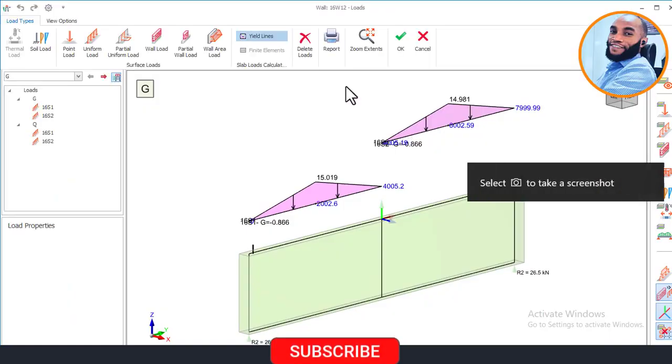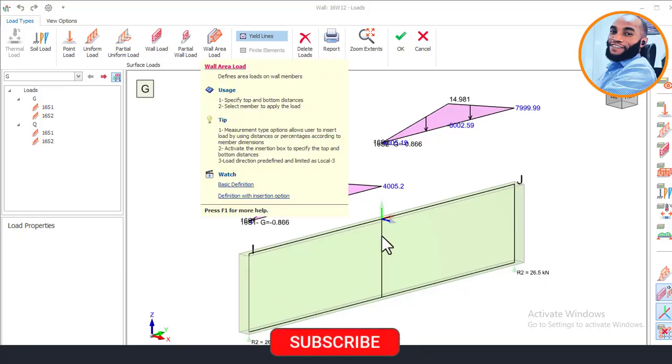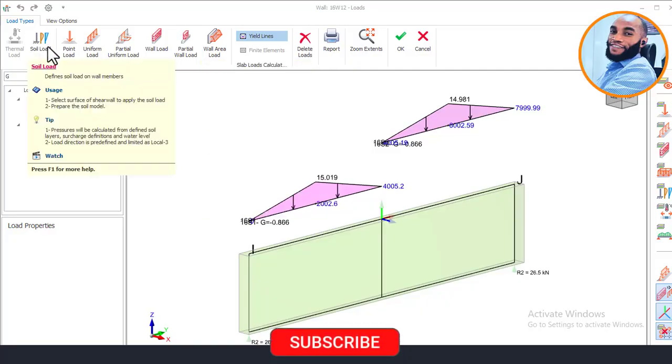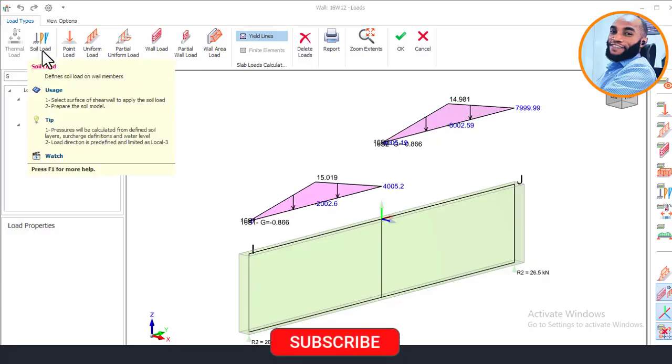On this Edit Loads, it will show you this interface of the load editor. On this load editor, I will come to this place that says Wall Area Load. There are two ways to load a retaining wall. The first way is to use the soil load, and the other way is to use the wall area load. The soil load looks more complicated for beginners because you have to define everything by yourself, inputting everything yourself.